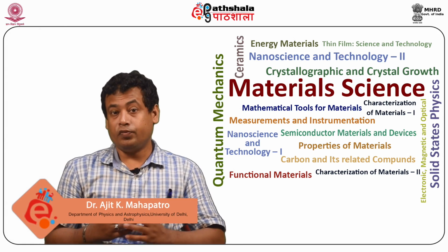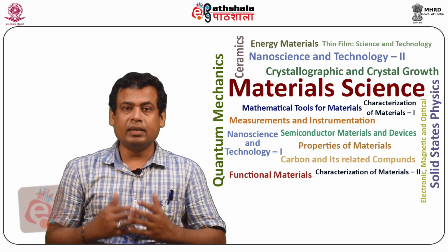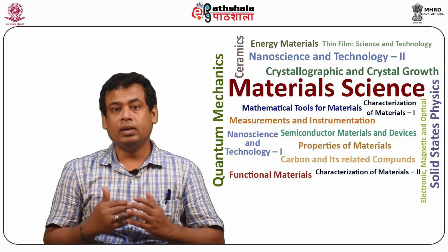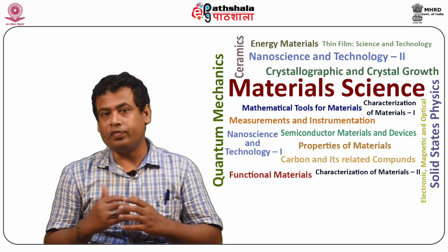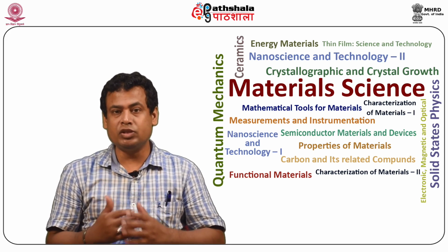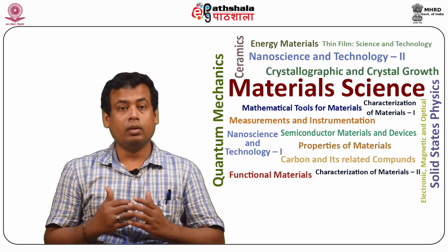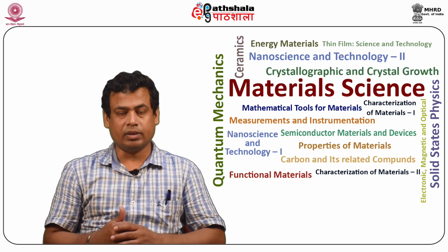The procedure followed during E-beam lithography includes pattern designing using CAD software and then writing on the E-beam resist by electron beam exposure, followed by developing the exposed wafer to take off the resist from the unwanted region of the mask. The resolution depends on a number of factors including resist thickness, density, writing speed and beam current.